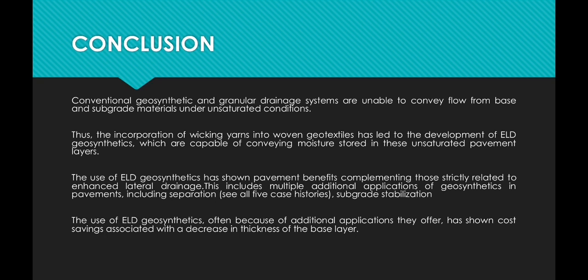The use of ALD geosynthetics has shown pavement benefits complementing those strictly related to the actual lateral drainage. This included multiple applications of geosynthetics in pavement, including separation, subgrade stabilization. The use of ALD geosynthetics, because of the additional applications they offer, has shown cost savings associated with the decrease in thickness of the base layer.